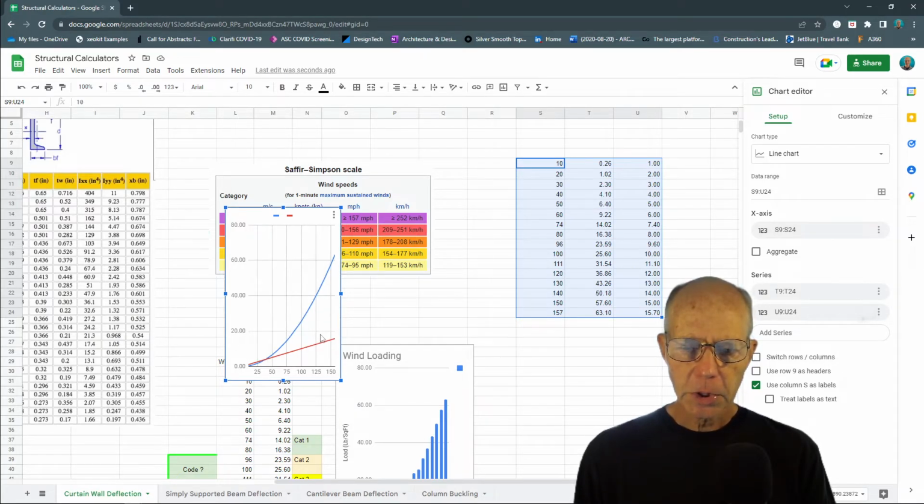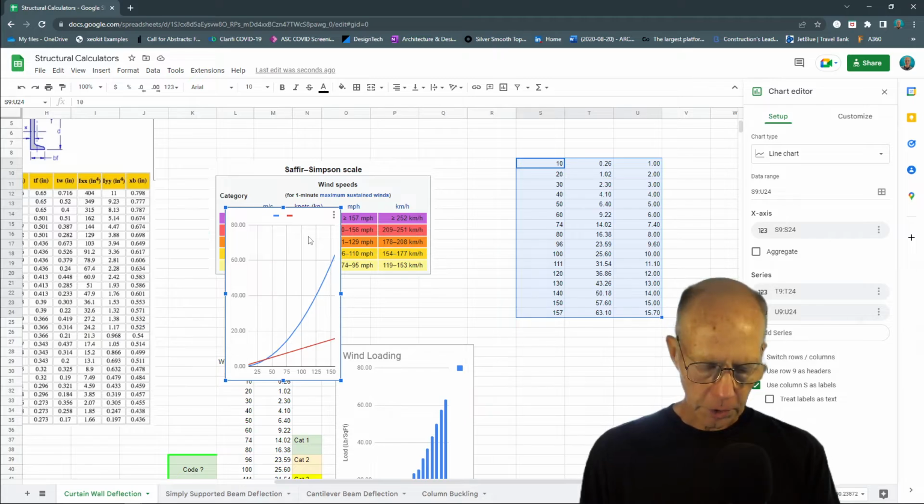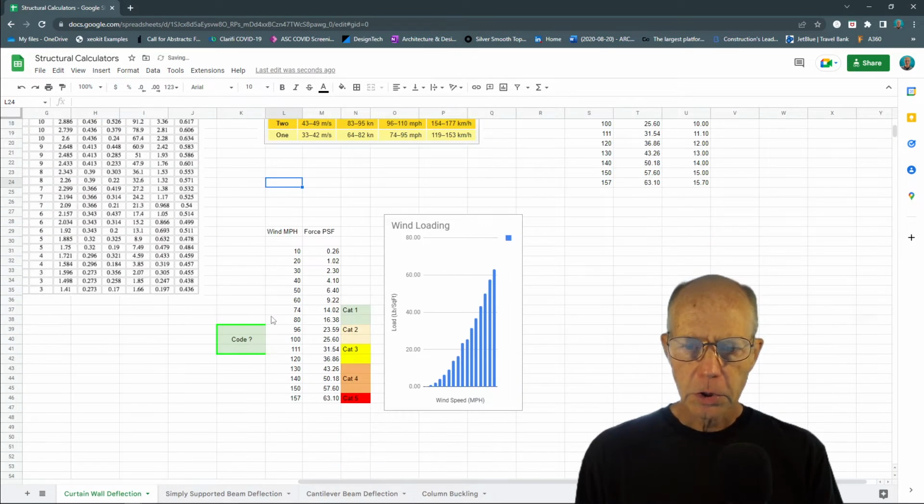So these high speeds contain a lot of, if you think about the idea of the force that's available, you think about this area under the parabola. In calculus, we learned that we can calculate the area under a curve. And in this case, notice the difference between what we would think if it was just linear increases in wind speed and if it was a squared function, how much more force is available to deflect our structure. So that's really why I want you to go through this kind of exercise, at least to start to gain the first idea about wind loading.